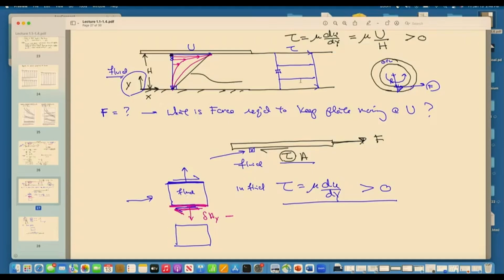Take a look at this fluid element, okay? We're going to discuss further what happens to a fluid element in a flow. We already know that it gets deformed. When there's a shear, what was cubical gets deformed like this, and so there's an angular deformation. But when you have a shear, when there's higher velocity here than here, it's also going to rotate the fluid element. That rate of rotation is vorticity.